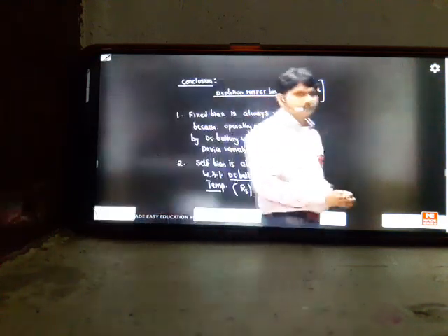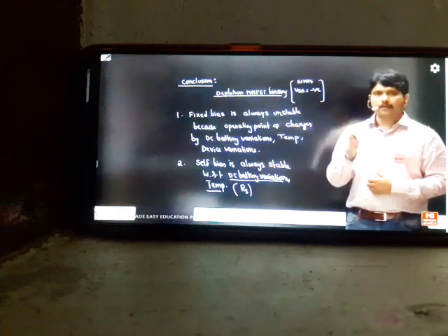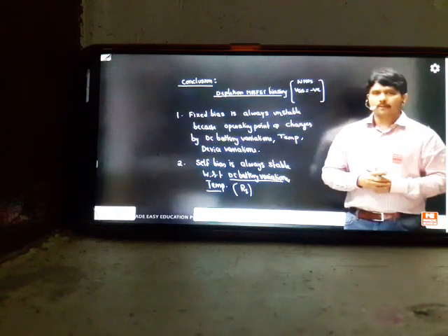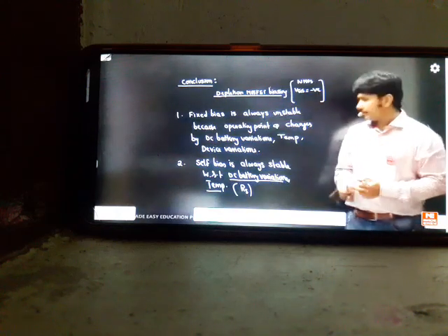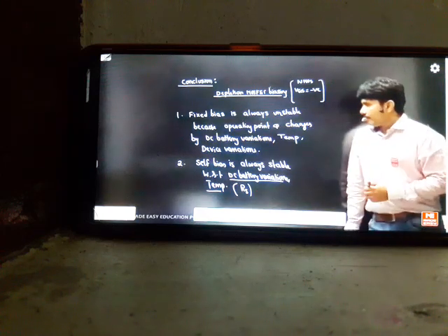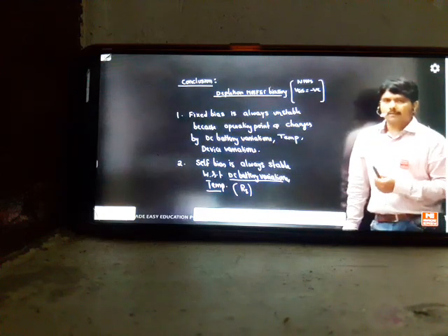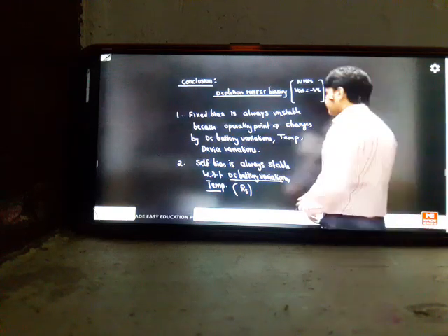RS is a negative feedback resistor, which we have already experienced in BJT classes. Whenever you keep an RE resistor, it gives control for the VCC variations. It also controls the temperature. This RS always controls these points. But device variations, it is not controlling much.